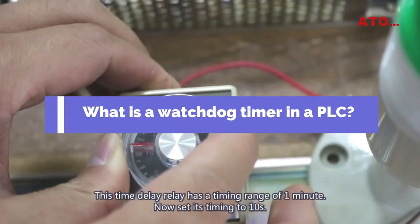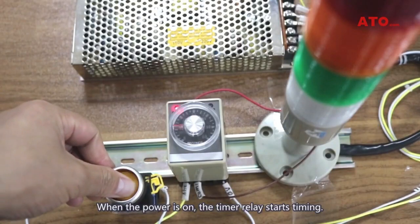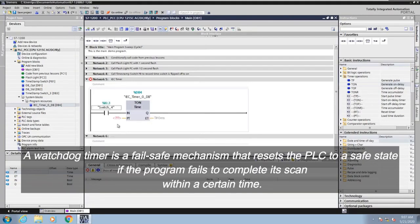What is a watchdog timer in a PLC? A watchdog timer is a fail-safe mechanism that resets the PLC to a safe state if the program fails to complete its scan within a certain time.